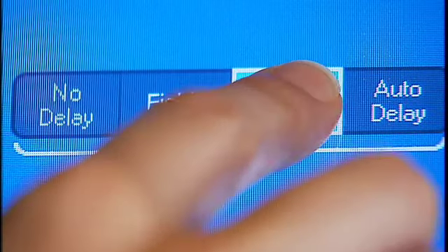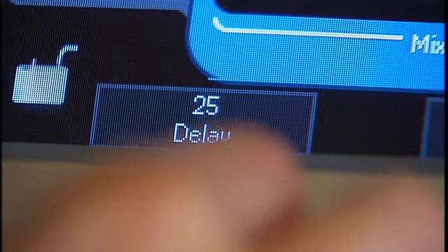The last tab is for input delay. Using this input delay will allow you to correct for the differences between incoming video and audio signals. You will notice that you can set the delay by fields, milliseconds, or an auto delay. Auto delay makes Indigo match the audio after any differences caused by internal video processing of keys or scaling. As usual, setting the delay is done using the digipots.